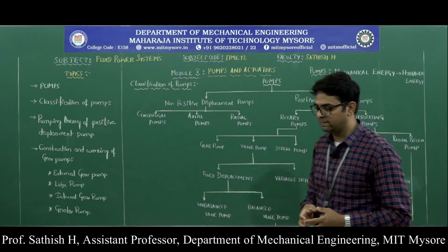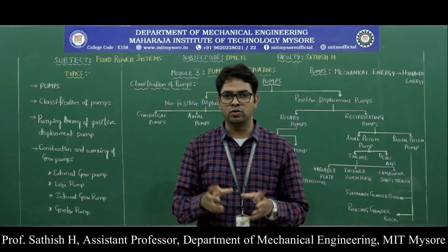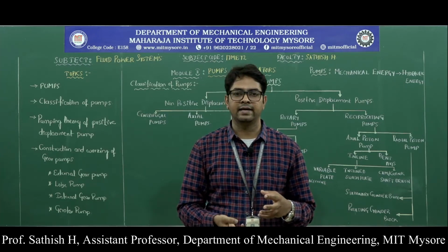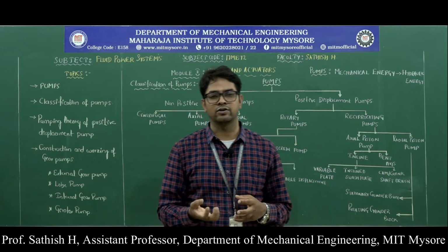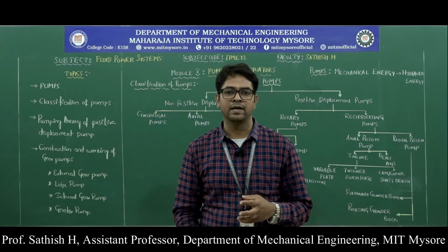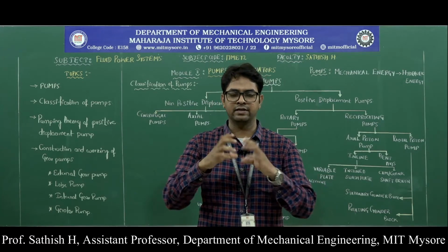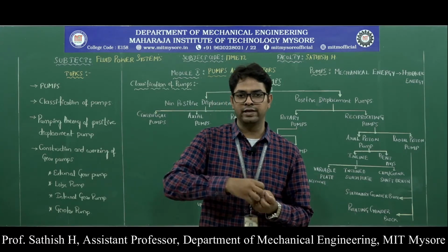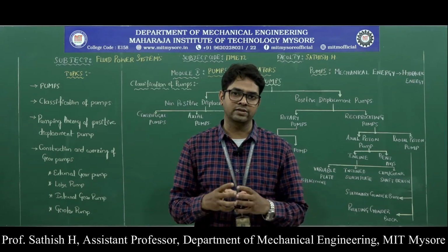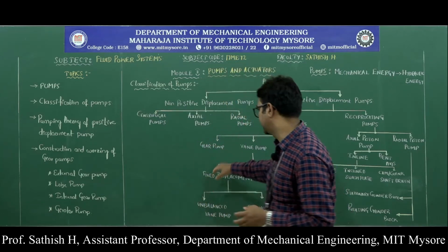In the case of gear pumps, we have two gears inside the casing. When one of the gears is rotated, it creates a negative or vacuum pressure. Because of the pressure difference between the inlet and the reservoir, the fluid is taken in. While the two gears rotate, the fluid is carried between the teeth of the two gears towards the outlet. That creates the higher pressure, and that is called a gear pump.